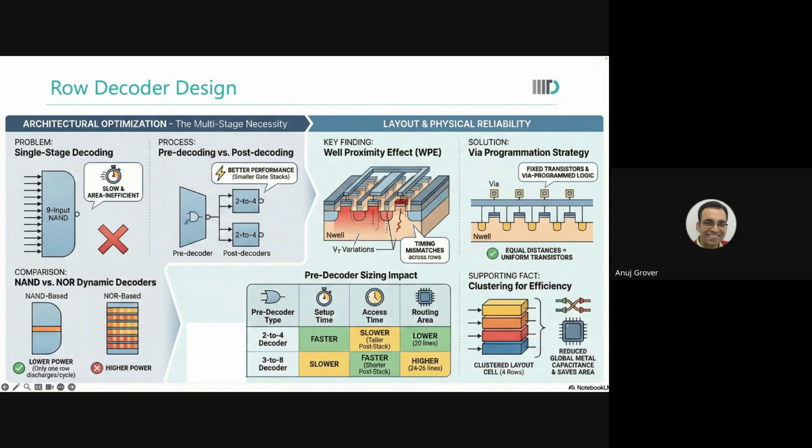You are basically asking like we are having multiple rows and instead of that we are selecting one long column? No, I'm not asking anything like that. I am saying in the videos we had clearly said that you will not make a row decoder per word line. You will make a row decoder for a pair or a four set of word lines or eight set of word lines. Why do you do that?